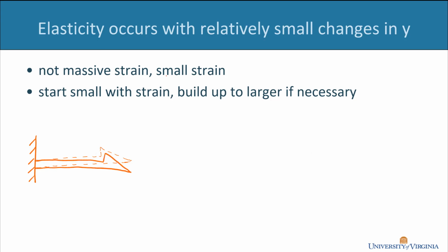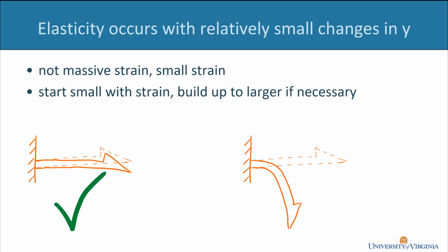So remember, the amount that you're actually moving the part is the deflection. And this amount of deflection, roughly, is okay, good. For PLA, the material that we're dealing with, if you were to design a part that required this kind of deflection, not good. There's no way it could do that. It would just snap. It would just break. So that's just knowing that we're working with a brittle plastic, and in order to stay in that elastic region, it has to be relatively small amounts of strain.